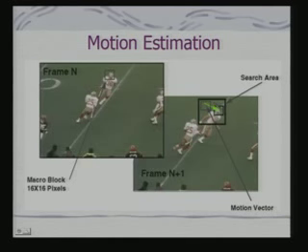When we are using a combination of forward prediction as well as backward prediction, we get B frames. You can realize obviously that computation of B frames for the purpose of compression is computationally most complex. And in video telephony and video conferencing kinds of applications, we typically do not use B frames. We use I and P frames.